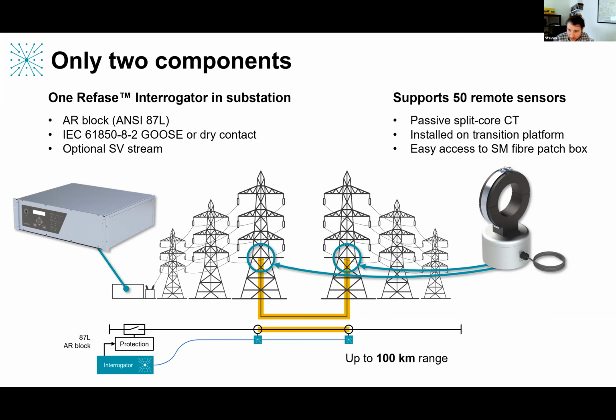Yeah, sure. What I'm really interested in, from a protection point of view, is what happens in the first few milliseconds of a fault occurring. And this gives you, as Campbell was talking about earlier, sort of perfect discrimination through unit protection, through differential protection. So as long as the cable section is contained within that zone of unit protection, then without any ambiguity, we can determine which section the fault occurred in.